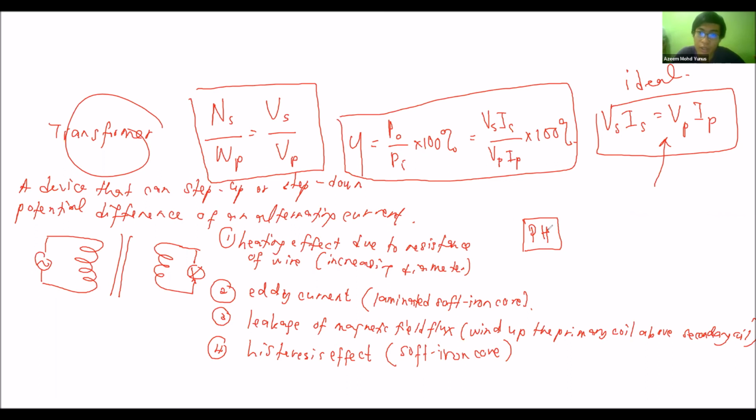the turbine rotates inside the magnetic field, causing relative motion, causing changes of magnetic flux, thus producing an induced current. So where do we go after that? We have to step up the voltage in order to reduce the current. So with higher voltage, the current decreases.